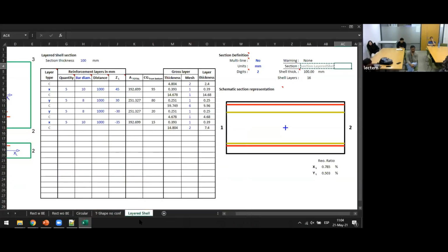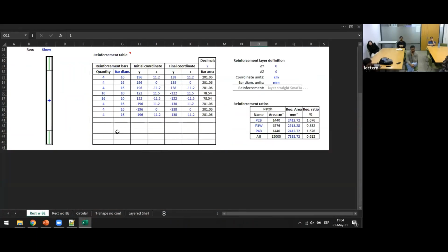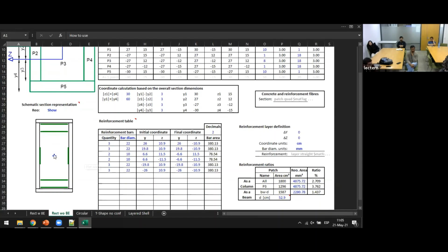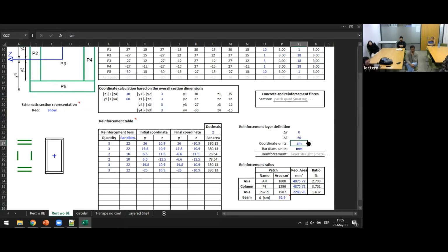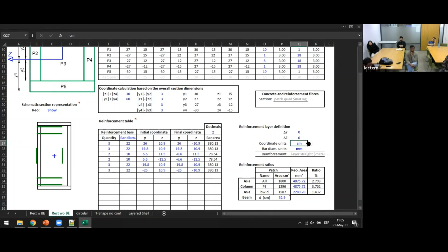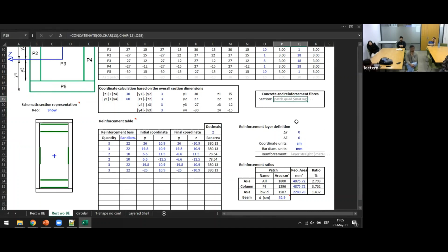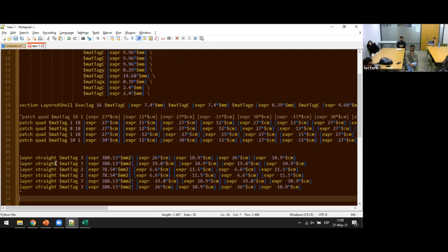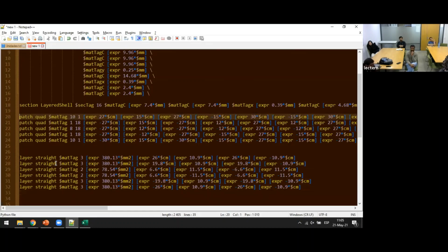And that is the same idea for, let's say, for example, a beam. So I have overlapped the two things. And if I say I want an offset of 50, well, I can see that I'm taking that reinforcement off the section. So once I have everything, I just copy that cell, paste, and I have everything again. The only thing that I need to be worried about is to delete those quotes, but then all the section is there.